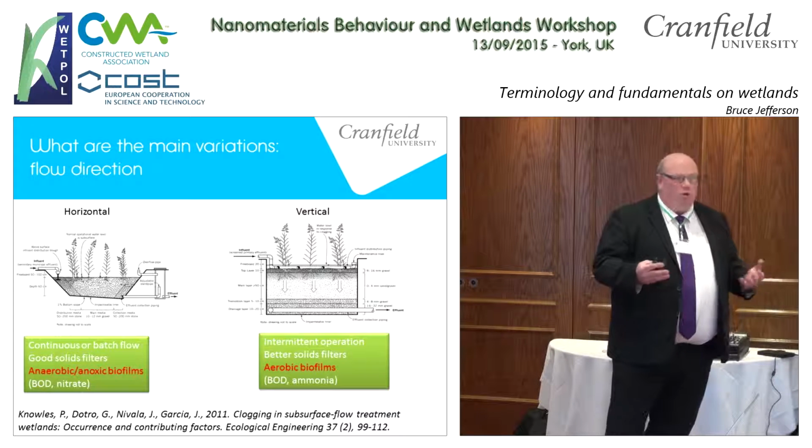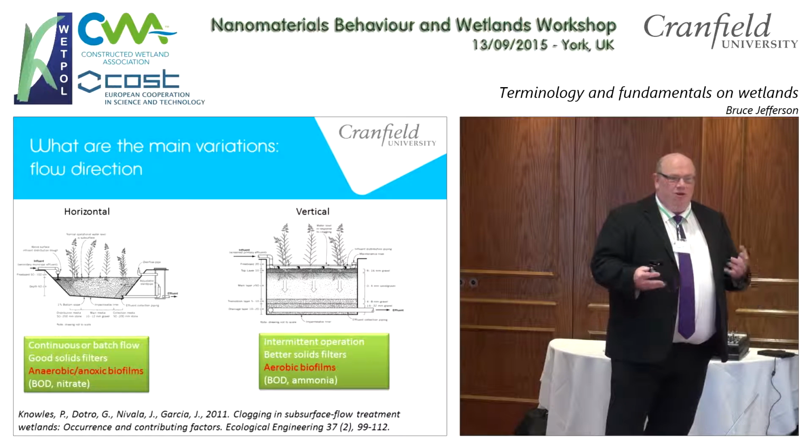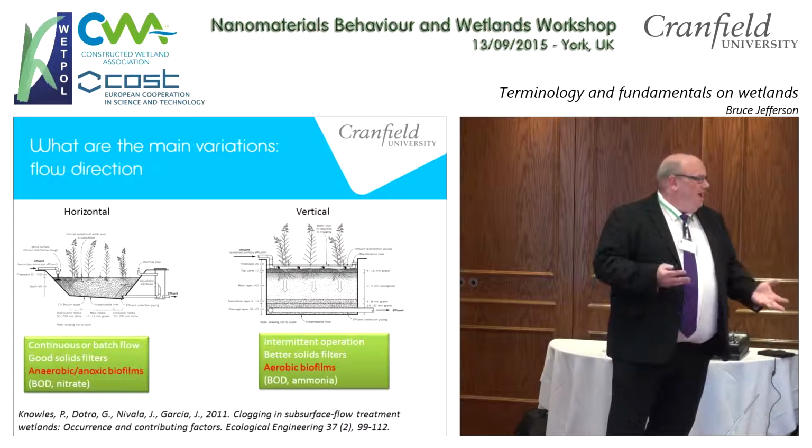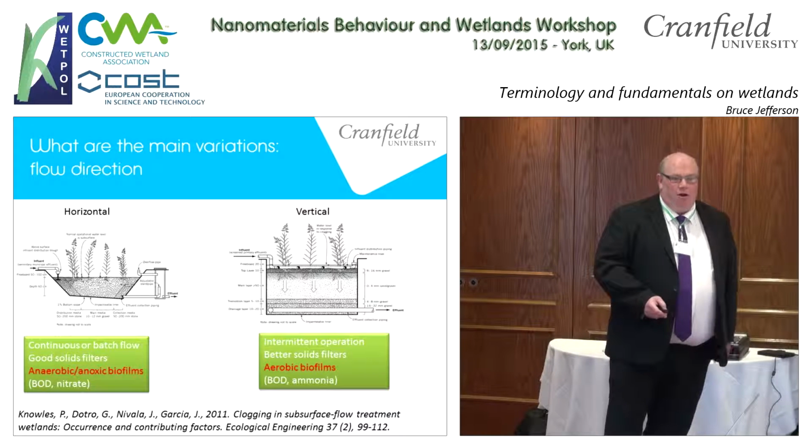So just by choice of which flow direction I'm using in my wetland, how I have to think about the fate of nanomaterials and colloids is going to be very, very different. The sorts of chemical and biological reactions that could occur in those different redox chemistries change the situation quite a lot.